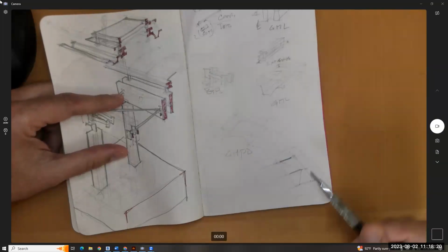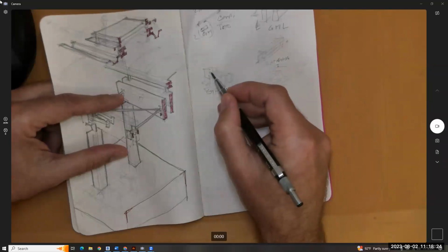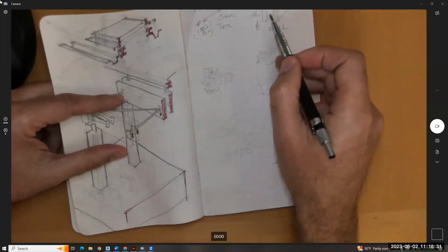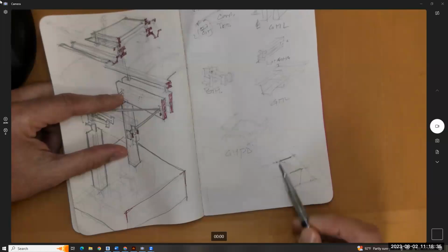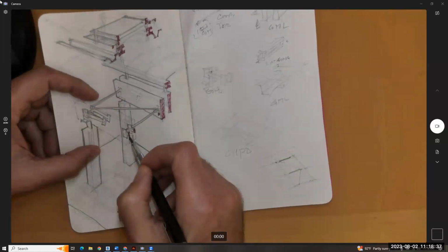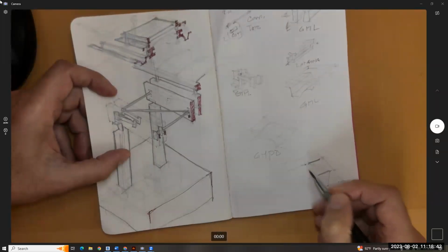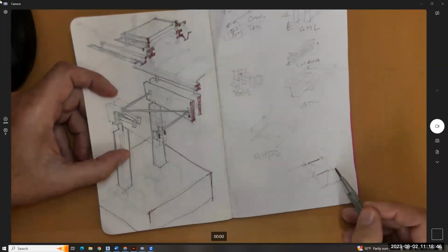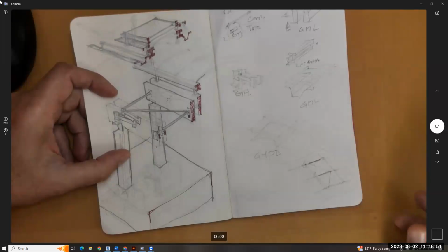Well, this bracket, I'm going to come in and I can snap right to that node because I'm going to build this to where the center line of that pipe that's crossing between the two is the exact location of that node, right? Because it's the center of this whole thing. The center line of this pipe right here is exactly at this node and this node. So I'm going to snap one in here and snap another one in here. That will repeat to this side and that will repeat to this side as it goes through, right?